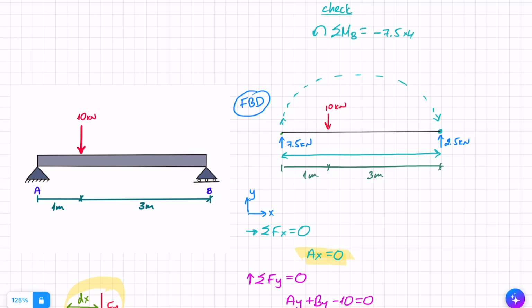Then I've got the 10, which is the line of action of the 10, and then it has to return to this point here, to point B. So it's giving me a positive moment, or a counterclockwise moment, so plus 10, and the distance is the distance between its line of action and B along the x-axis, since it's on y, and that is 3 meters, so times 3, and that works out as minus 30 plus 30, and that is indeed 0, just as we're expecting. So tick there, and I can assume that my results are correct.